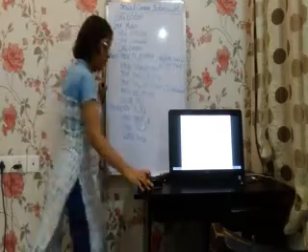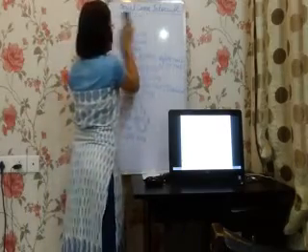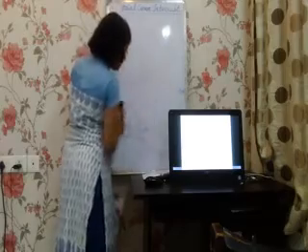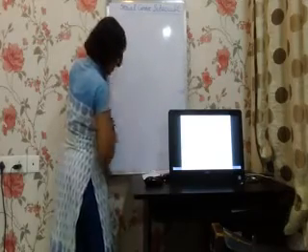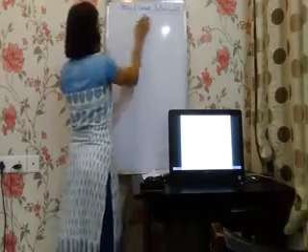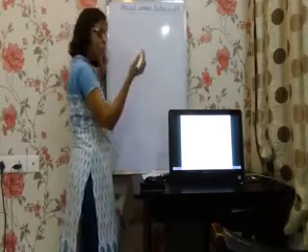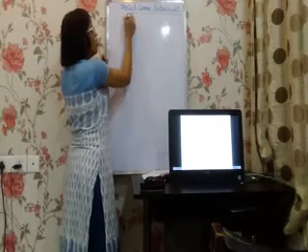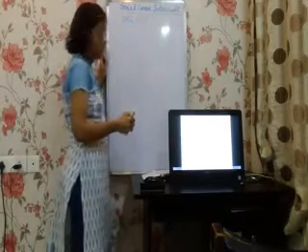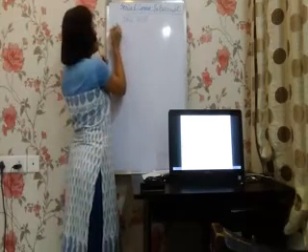Now let's complete the remaining part of the program. Now what is remaining? Only the serial communication interrupt program that we are supposed to write. Okay, what we are going to do in this program? I'll take any random address. Suppose I take ORG 100H, any random on chip address. Okay, and I start with my serial program.